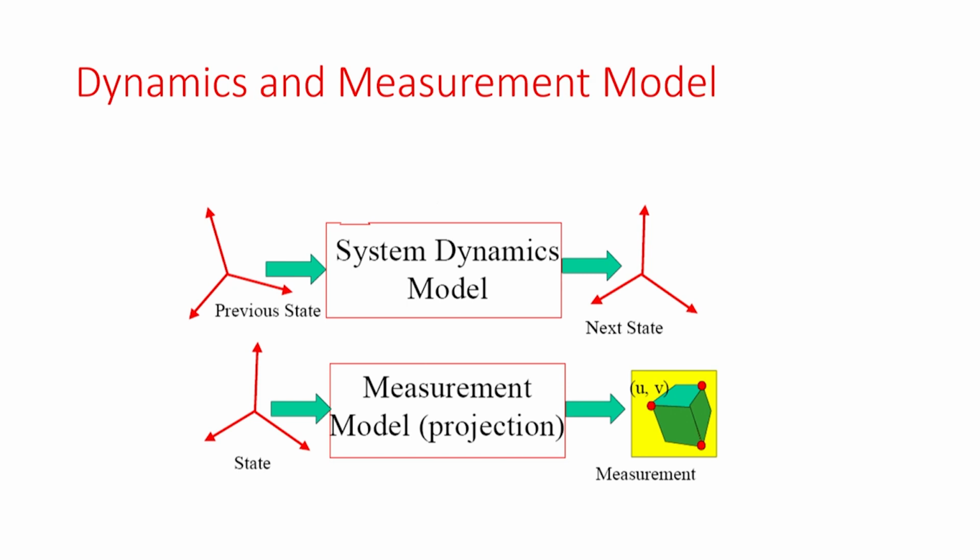Let us understand this. Tracking means you want to compute the state trajectory of any vehicle or any system or any kind of object, through your sensor. Your sensors could be radar, any type of radar: pulse Doppler radar, FMCW radar, CW radar, or passive radar. It could be your camera, your electro-optic or IR sensor, your LIDAR, or your ultrasonics. It could be anything. So, this is your measurement system.